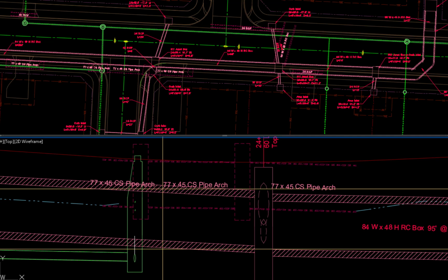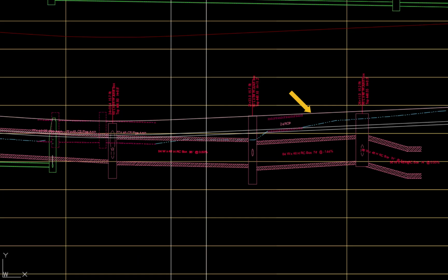Where possible, there should be a minimum of 12 to 18 inches clearance between the bottom of the curb and the top of the RC box to allow space for the installation of water and gas mains and service pipes. A temporary layout polyline is drawn along the Kincaid south side or right top of curb profile. Two copies of the temporary top of curb layout polyline are shown.